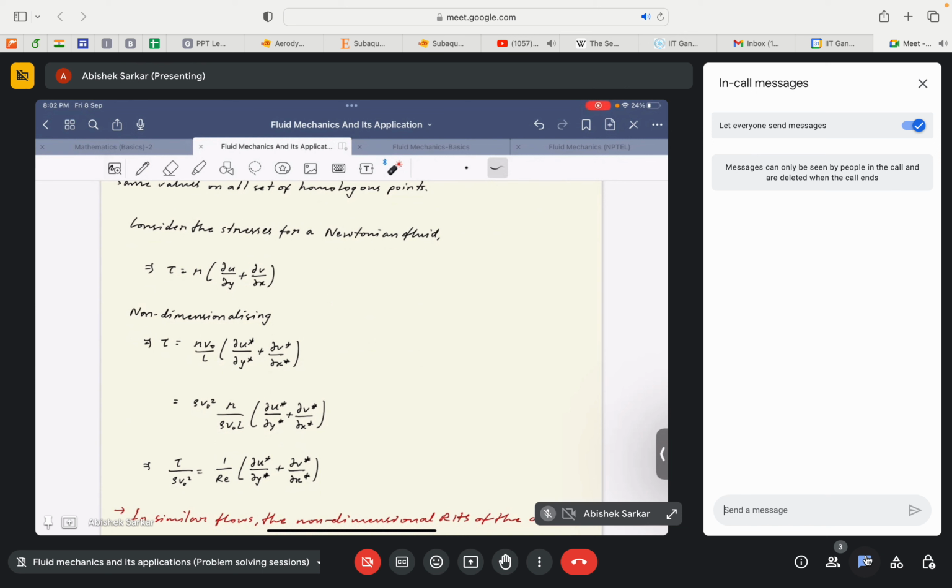In the case of pipe flow, you can take the average velocity as the characteristic velocity as well. So that's why I'm mentioning how it can be different. But usually for most of the cases, v naught is the highest velocity, or the largest magnitude of the velocity, that the flow field can achieve.